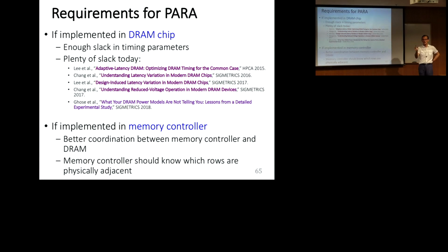What is the relationship of the P such that P doesn't need to be random? Even if you use a count of which row, note that the memory controller can access the row so many times between refreshes. Doesn't matter which. The worst case, it accesses the same row. If you guarantee that you do this every, let's say, 500 times, and it needs 510, even in the worst case you won't hit. Yes, it's like a finite budget. Exactly. If I guarantee that, tell me how many you can do, if once in that many I do activate, then there's no way you can hit me. Exactly. I agree with you, but that depends on the value of P. You need to select P very carefully such that you don't need to be random. But we can take it offline.